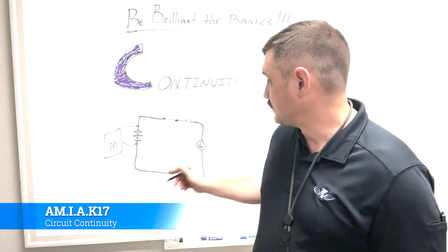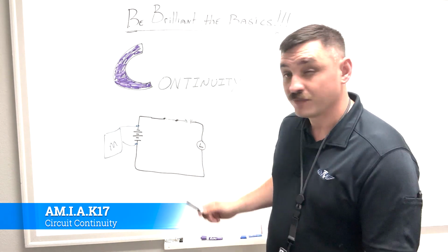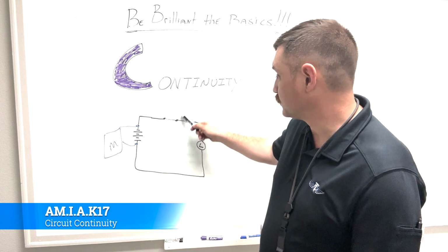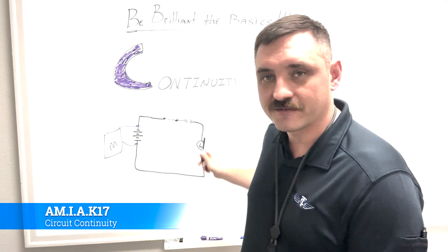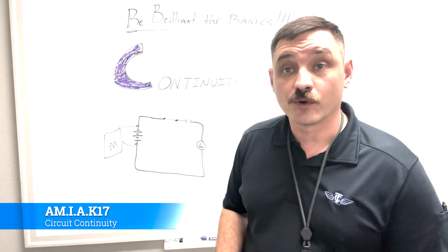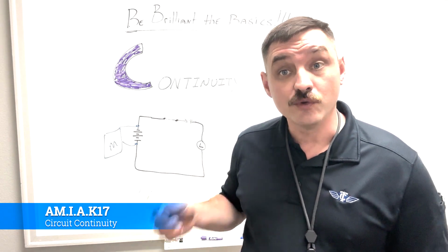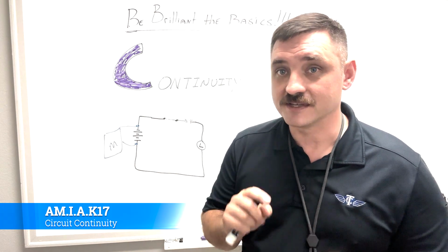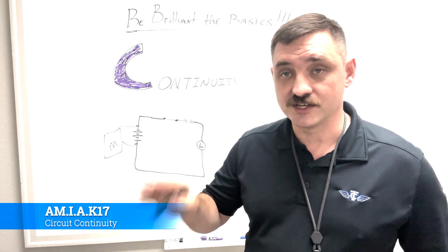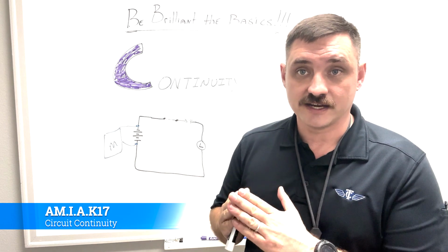What's happening is that you technically still have continuity, but it's through the atoms in the air, which is infinite resistance. So you'll never get this lamp to come on. And therefore it won't ring, it won't beep, it won't do anything. And you know that you have a problem, and you know that the problem is a continuity problem. It's not a voltage problem, it's not anything else. It's literally just the wires aren't connected.